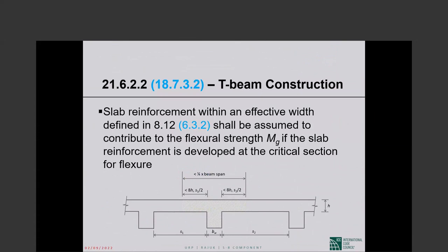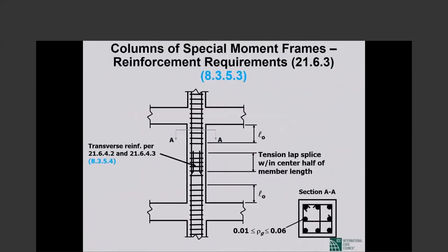So do include the contribution of the slab top reinforcement within the effective width to the moment strength of the beam.